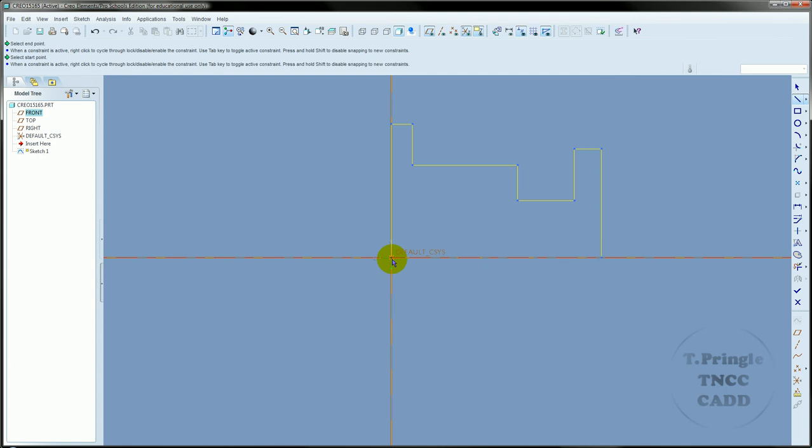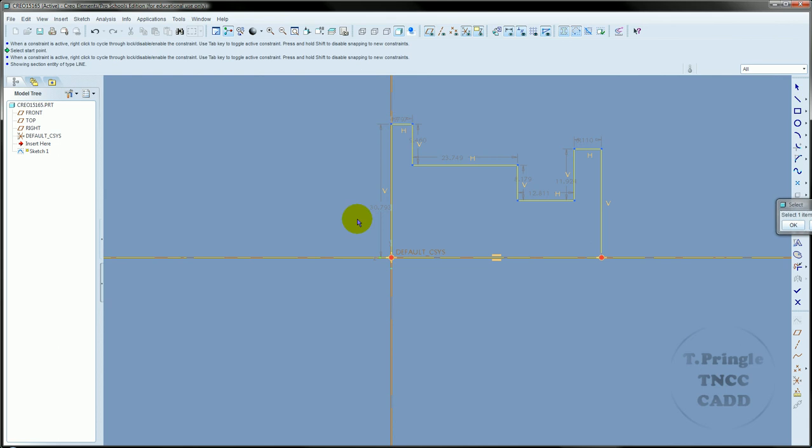Now, I'm going to leave it open-ended down here for just a few minutes while I go through and put in some dimensions. Now, if you look, my dimensions are really far off, so what I'm going to try to do is rope in the diameter dimensions a little bit and then just continue dimensioning the object. So we'll place our first dimension, and because I have a geometric center line here, if I select the object, the center line, and the object again, it'll actually allow me to create a diameter dimension.